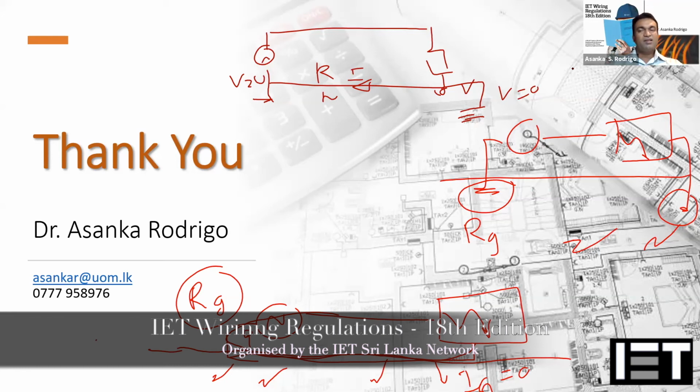Yes, as per the IET wiring regulation, all the metallic parts, non-current carrying, should be connected to the equipotential bonding. It doesn't matter whether it is precast or normal construction, everything should be connected together, so you have to find a way to connect them.